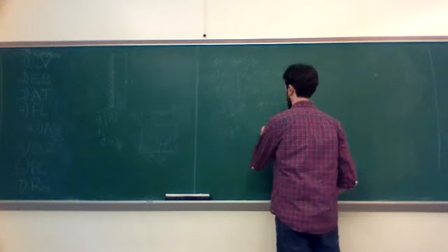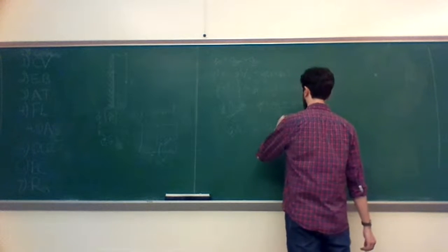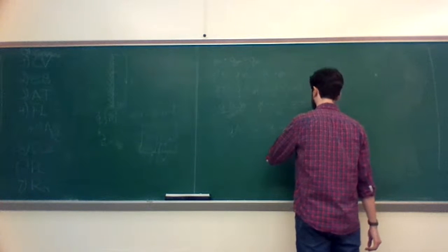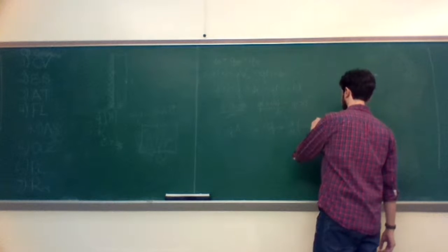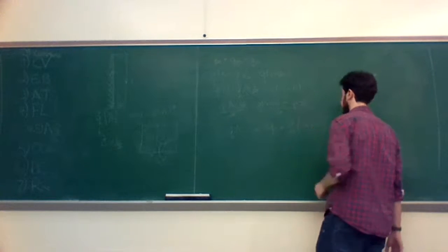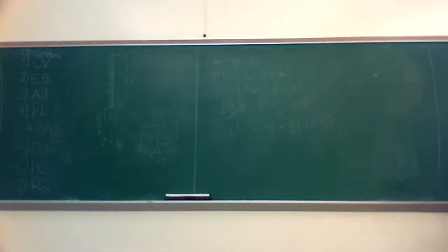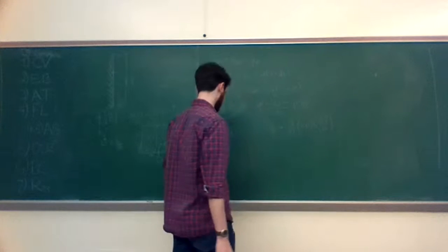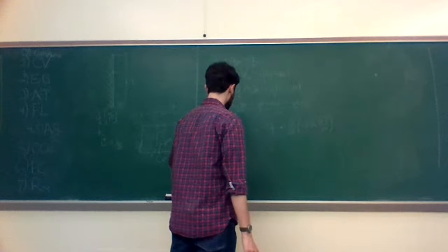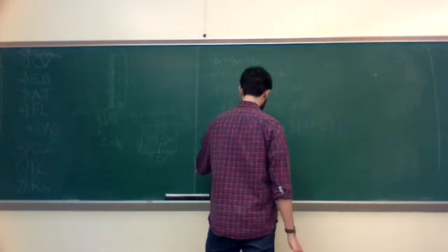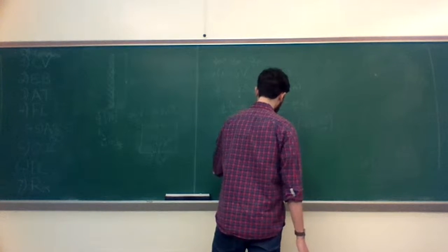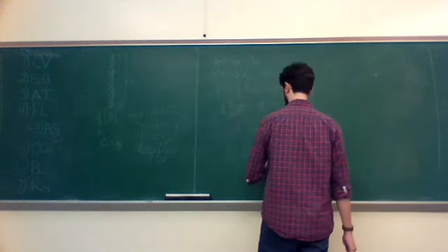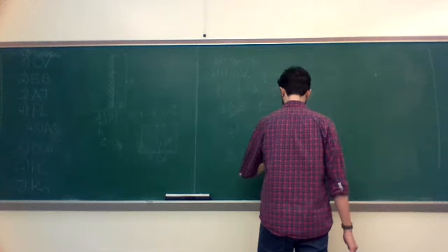Fourier's law. So Fourier's law, we're going to apply to Q, and we're going to expand out that Q term in d dx. I'll replace Q with negative k A dT dx. Okay. I'm going to rewrite this down here to make it a little cleaner, so I'm just going to swap the left and right hand side. d dx of negative k A dT dx equals Q dot.